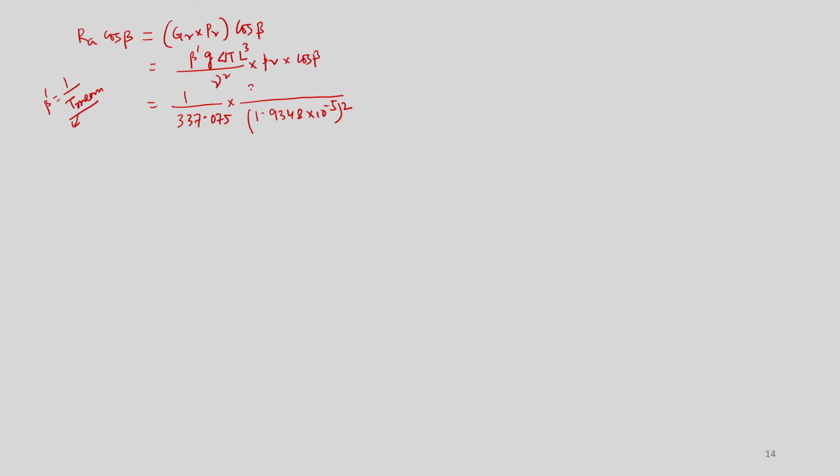Then we have delta T, 346.15 minus 328, and length means the distance between these two plates. So, this is 0.05, this is a characteristic length. And we have Prandtl number 0.7192, right.